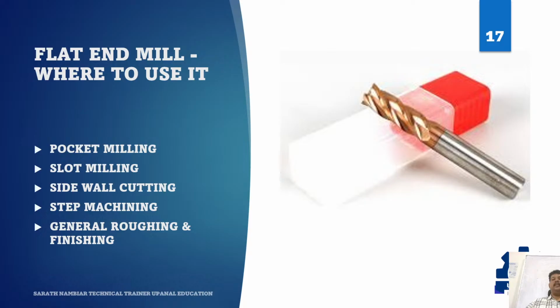Third, sidewall cutting. If a profile must be machined on the outside or inside wall, the flat end mill performs well. Fourth, step machining. Many mechanical parts have multiple heights, levels, or shoulders. This cutter handles those easily. Fifth, roughing and finishing. Depending on the cutter quality and strategy, the same tool family can be used for roughing or finishing. Now let's discuss the caution.